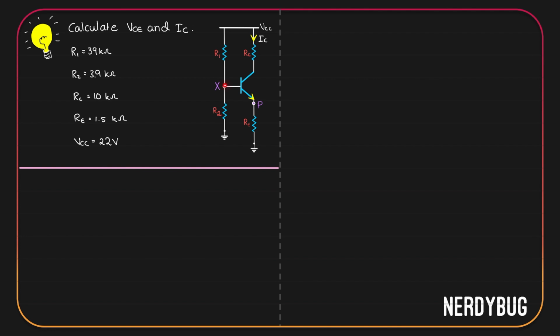If VB is lesser, IB will also be lesser. You already know why base current being negligible is important for voltage divider bias. So we need R1 to be significantly higher than R2. As a thumb rule, while designing a circuit, we take R1 to be 10 times R2. Now to solve the problem, I will redraw the circuit, but this time instead of the voltage divider bias, I